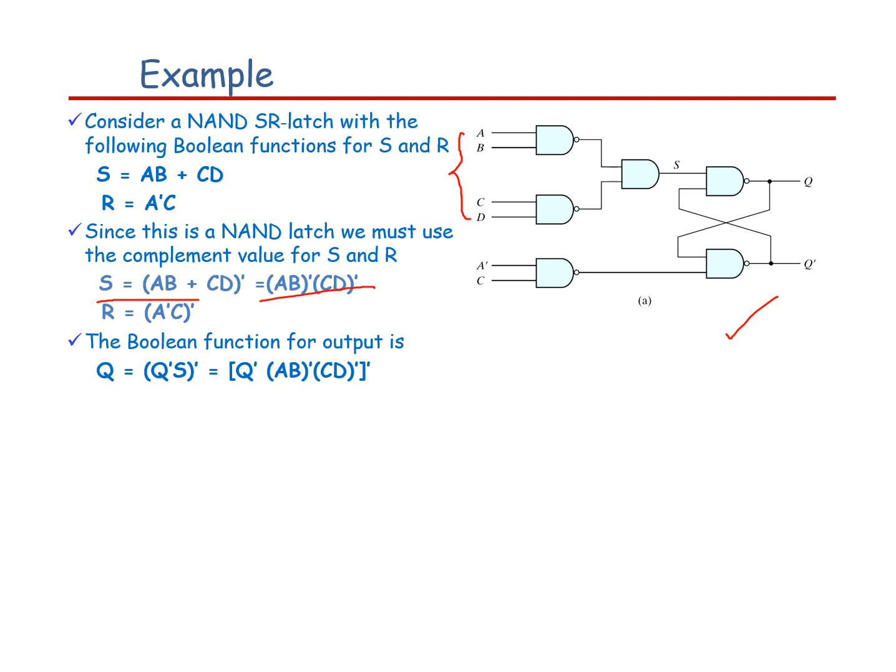Here, the Boolean function for output Q, a feedback is given here, Q bar. And then A dot B to the whole bar, and C dot D to the whole bar are also given to S. These three terms are going through an AND operation, and then inverted, so the Q output is a NAND operation.